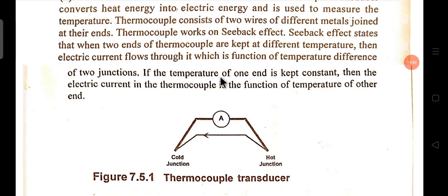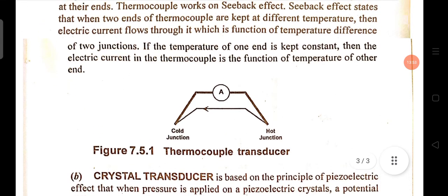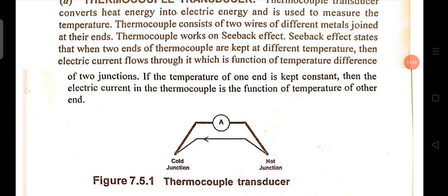If the temperature of one end is kept constant, then the electrical current in the thermocouple is a function of the temperature of the other end. That means the thermocouple transducer works on the basis of the Seebeck effect.